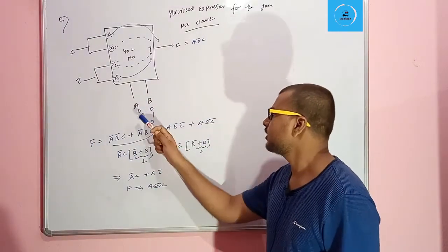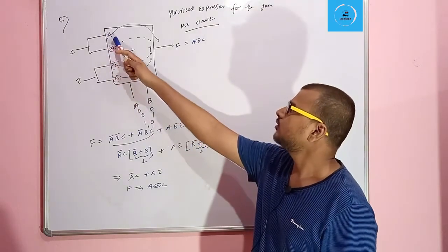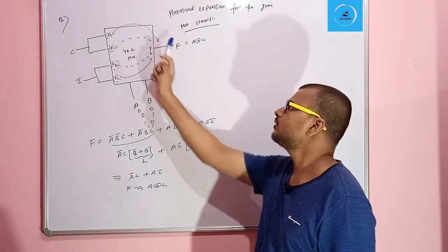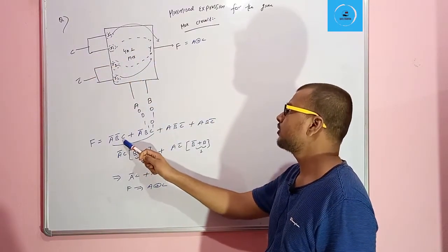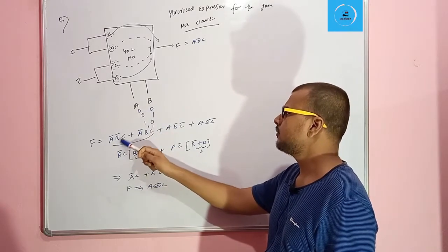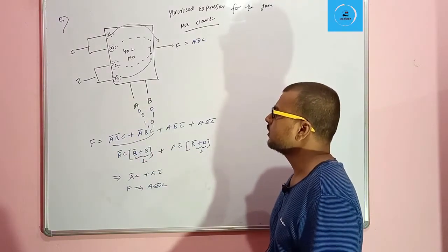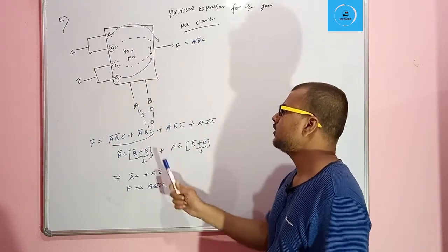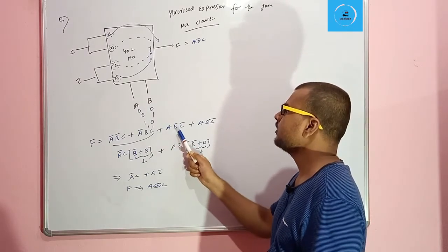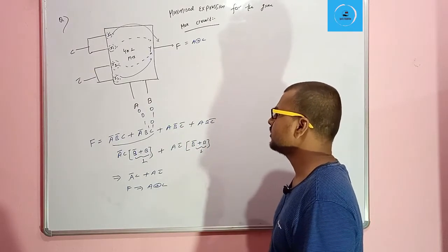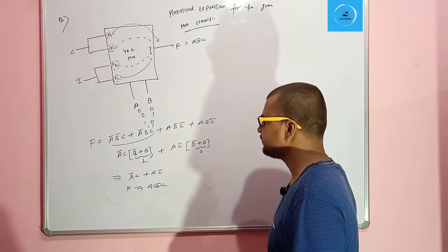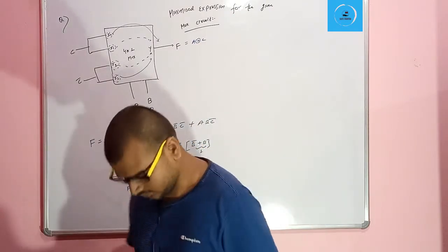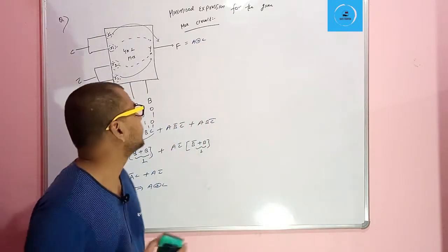So here when we have selected 0 0, then I0 will be selected to the output, and I0 is connected with the input C, so C will be present at the output. So for the first, A B 0 0, A bar B bar and C is the expression. For the second select input, A bar B and C. For the third, that is 1 0, A B bar and C bar, and for the fourth, that is 1 1, A B and C bar. Okay, this is the solution of our first question.